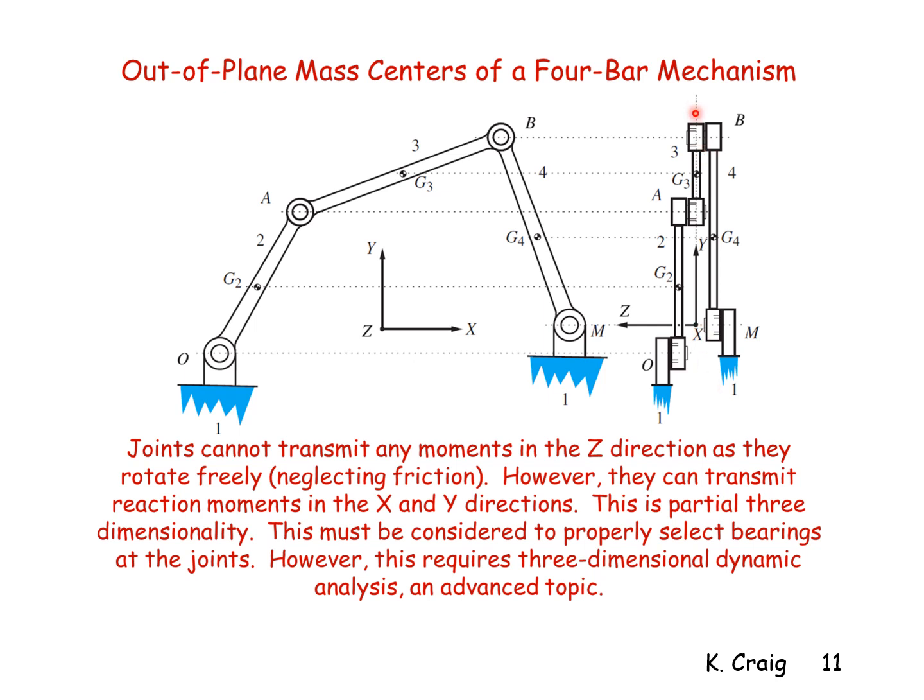There is a plane, an imaginary plane shown here in this picture, that the linkage moves in for analysis purposes. But here you see in reality, there is no plane motion. And so there will be forces and torques that act out of the plane of motion.